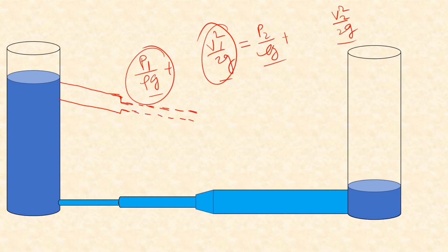Like this. And what does it mean? It means that although the total energy is decreasing, at this point the pressure has actually increased, and although there is a negative pressure gradient in this case, or adverse pressure gradient, P2 is greater than P1, flow will still take place because it already had a high velocity.